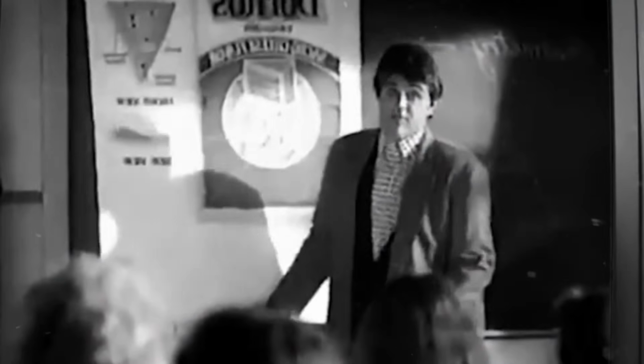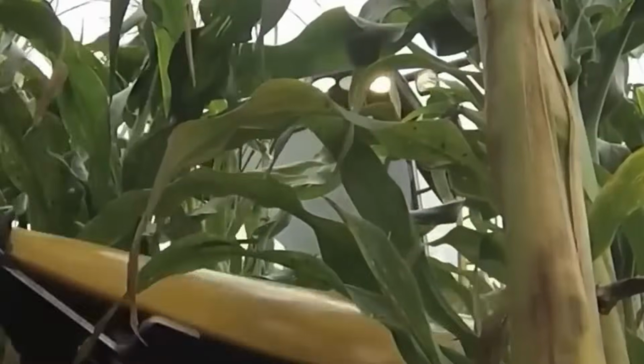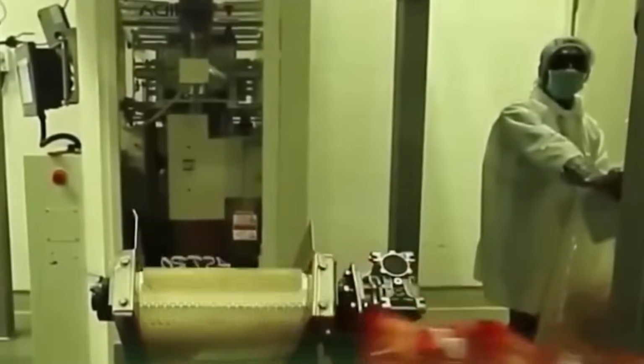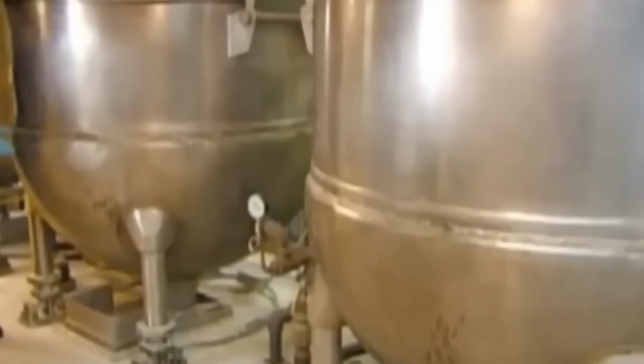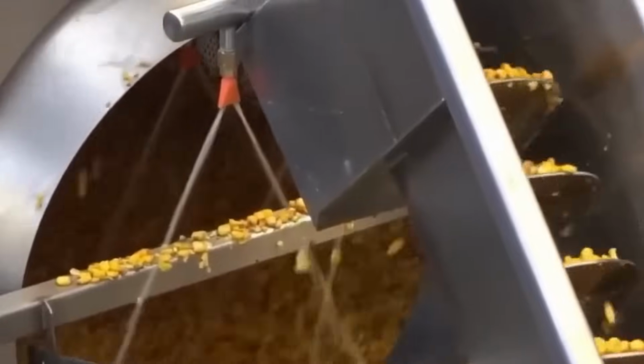optimization. Doritos are produced using a continuous process that begins with raw corn as the base input. The corn arrives in bulk and is stored in vertical silos with aeration systems to maintain stable moisture content. Each batch is gravity-fed into a cleaning system where the kernels pass through vibrating screens, destoners, and aspiration channels to remove dust, stones, and foreign matter. Magnet separators extract any ferrous contaminants before the corn enters the next stage.